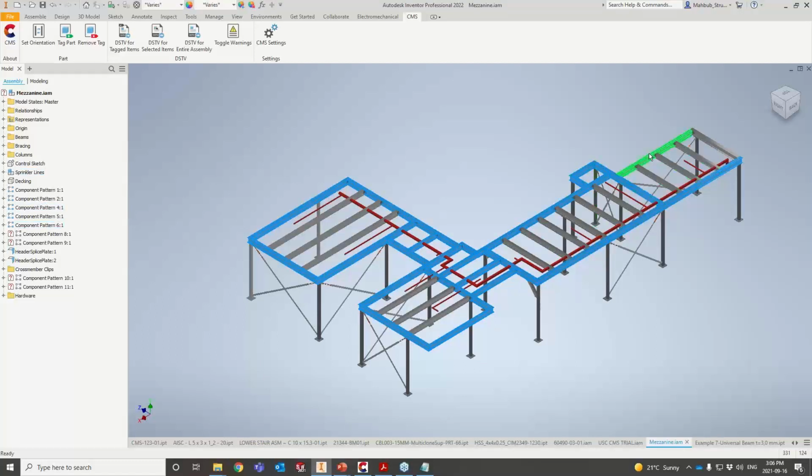Again, when you select members, you have to make sure that you have access to the members directly. So I cannot work on sub-assemblies. As you see, this is a sub-assembly here, right? So I have to go to that sub-assembly and work from there. I cannot run my sub-assembly from an assembly level, okay? So let me run the selected ones, hopefully that fixes my problem.